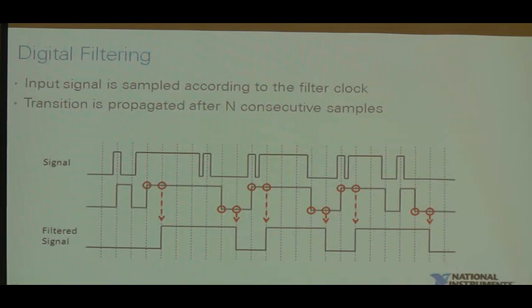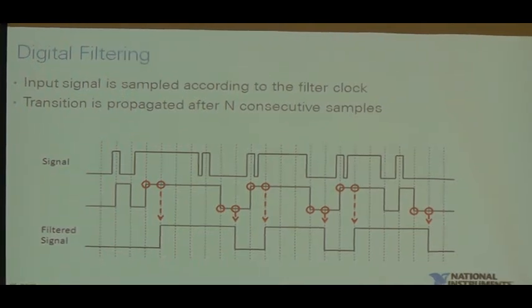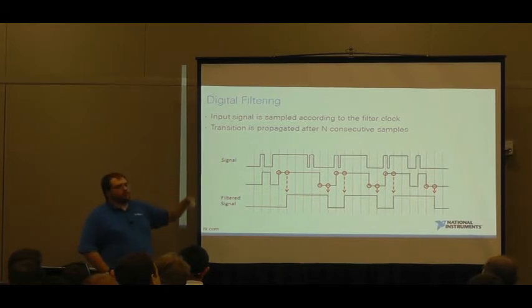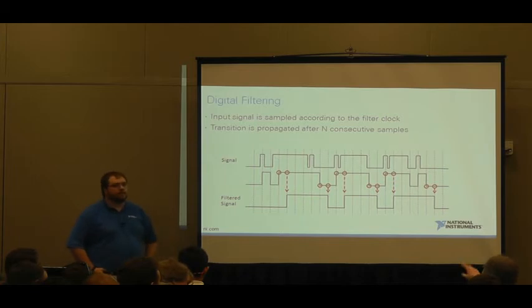So I specified 150 microseconds. DAQmx said I'm going to use the 20 megahertz time base or the 100 megahertz time base, and calculated that comes out to n of 57 ticks. Okay. So those filter times use your 100 megahertz clock, yes, the 100 megahertz clock on the right.